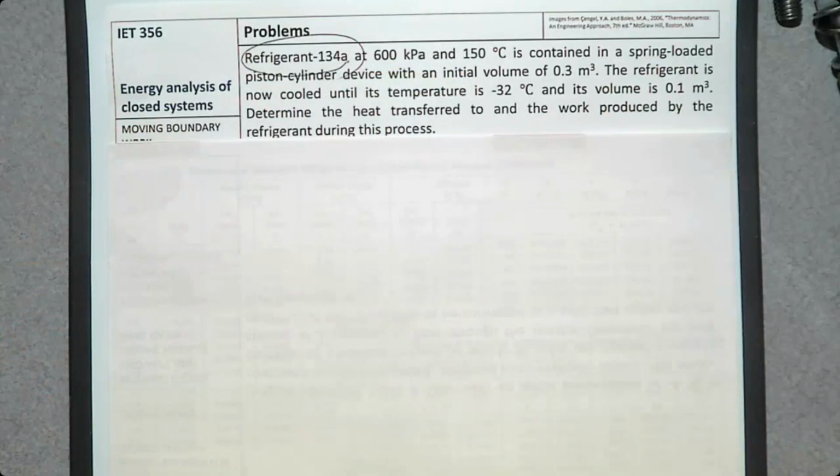So whenever we transfer heat from here to the outside by this air conditioning unit, can we use a single material like carbon dioxide? Yes, you can. However, the cost is going to be extremely high compared to using refrigerant that can undergo phase change.